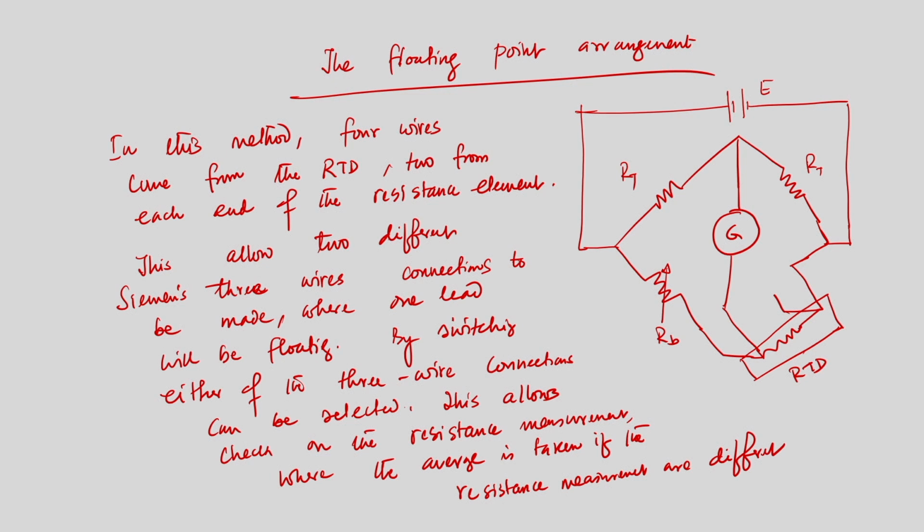So, today we have discussed temperature measurement using the electrical effect, and we have discussed the possible sources of error, and the remedies we need to have to eliminate the error. One such remedy is a defined wiring scheme, and we have discussed how, using this defined wiring scheme, we can compensate and balance the resistance due to the resistance of the leads, so that the measured temperature will not be affected.